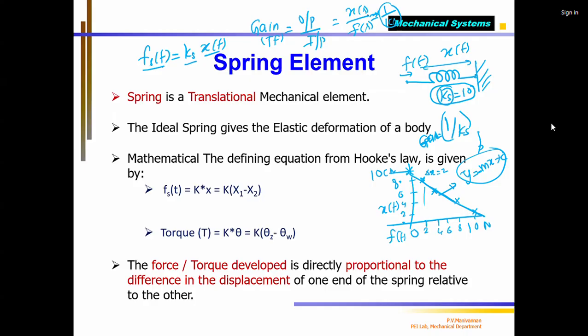Okay. So now for the spring, you apply a linear force. Instead of that, you know that if you take a spring like this, correct? One end is, this is called the B end. The A end I'm keeping open. B is connected, bonded or fixed. Now I apply a twisting force. I twist this spring using a torque. What will happen? Even if you twist one end, keeping the other fixed, the coil length will reduce, correct? As I twist clockwise, it will reduce. If I twist the other way, the length will increase. It is as if applying a linear force.